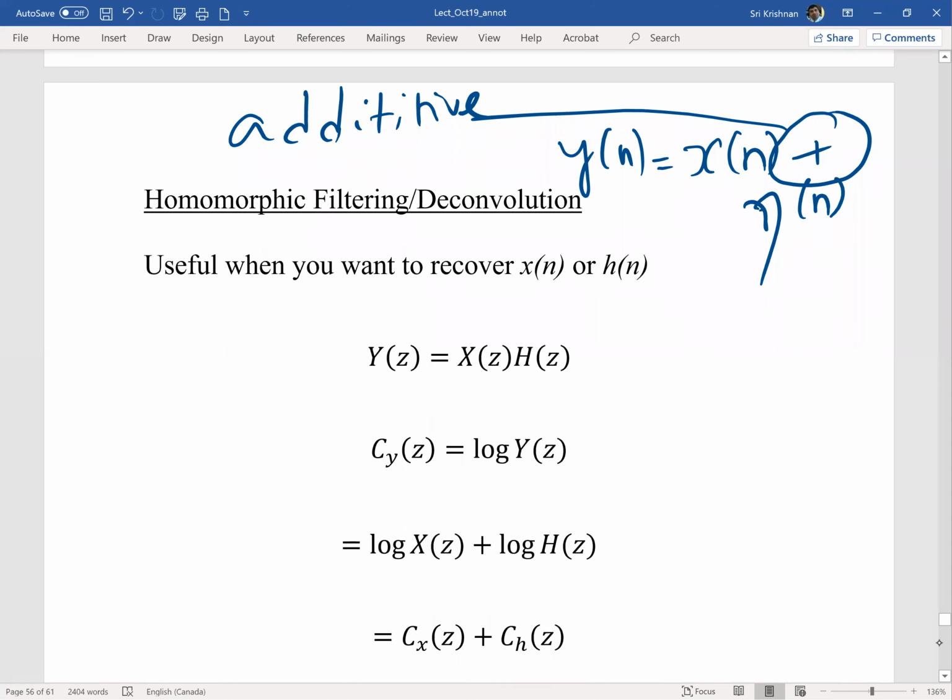When I know this is additive, then obviously when I use a low pass filter, we assume the noise to have high frequency, and this is eliminated. That's what we have been doing by assuming things are additive. But as I indicated, practically we don't know. There is a possibility your noise would be multiplicative, or your noise could be convolved with your signal of interest.